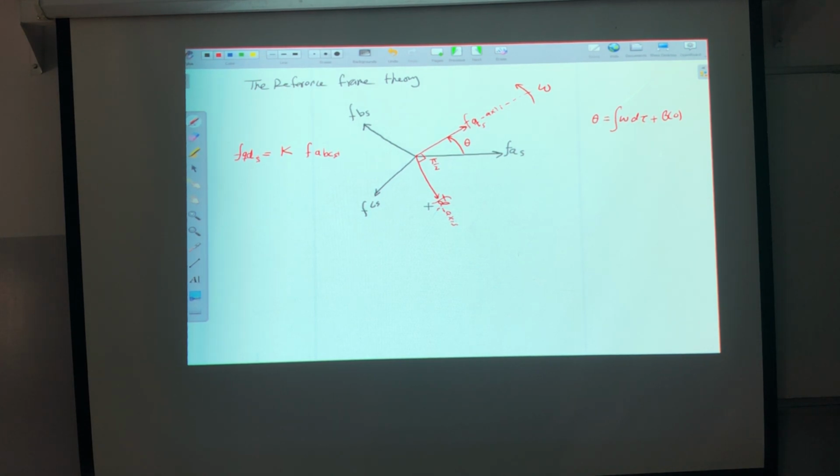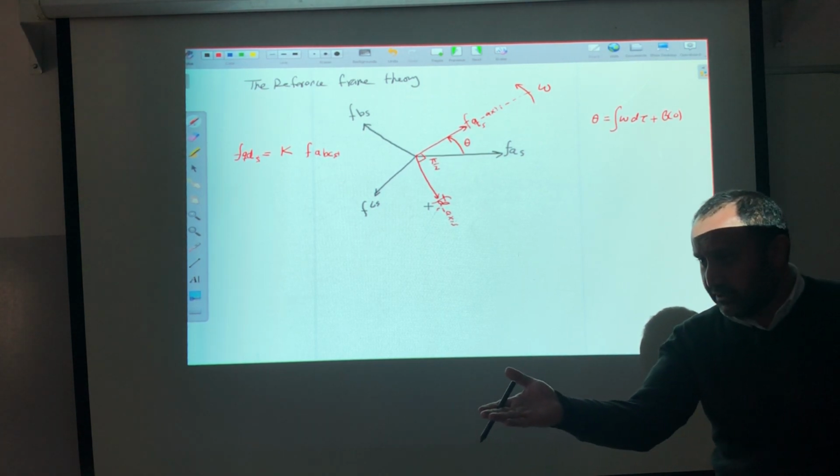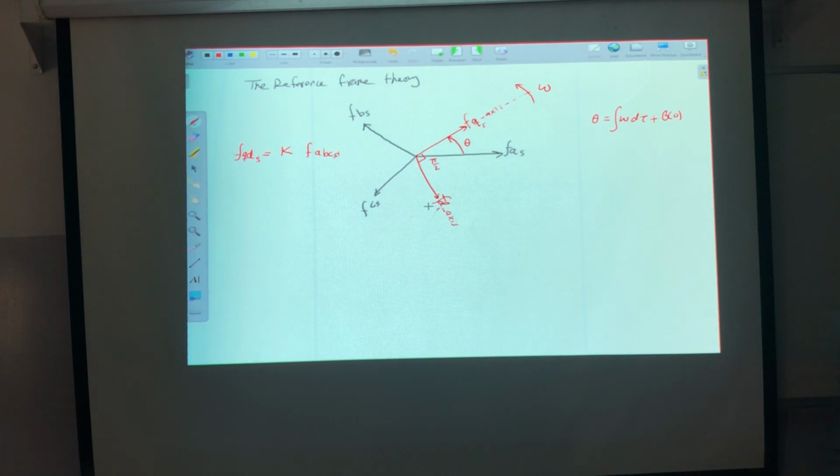So someone will say, square the matrix, man. This will be 2 by 3. And if you need to find the inverse, of course, we can do it with a pseudo inverse. So someone says, square the matrix. If I need to complete it, I will complete it with something trivial, the trivial solution. Do you know the trivial solution? 1 is equal to 1. So someone will say, complete it with the zero sequence. VA plus VB plus VC is equal to 0. So someone will say that here add 0. So this will be 3 by 3. So the last line will represent the zero sequence. It's a trivial thing.